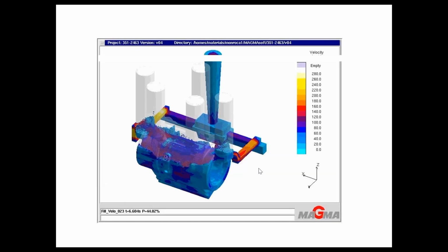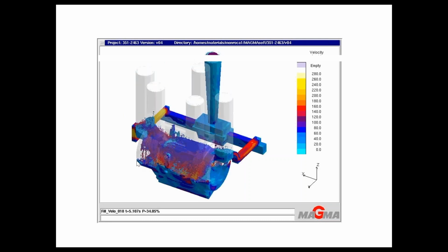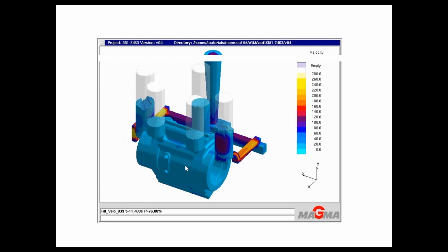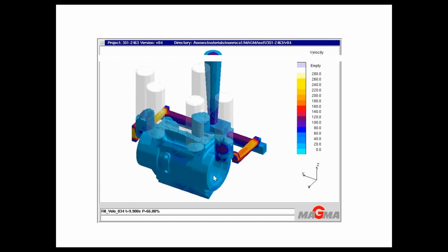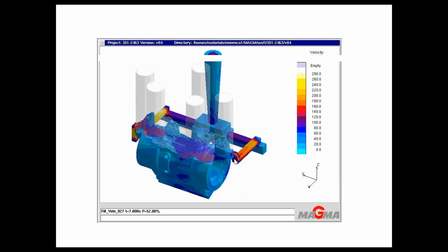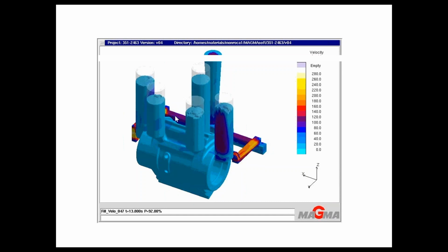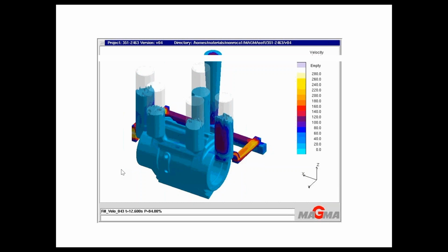So in steel castings, we actually pour liquid metal into a mold. So this is the shape of the part we want. And you can see the liquid allows us to make complex internal shapes, complex external shapes directly from the liquid material. This is the gating or plumbing system to let the metal in. And these tall cylinders are the risers to make sure that the casting is sound.